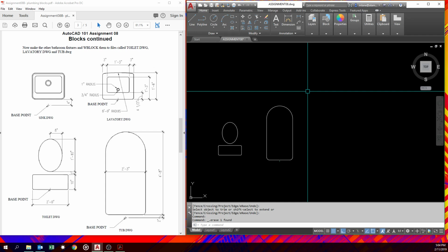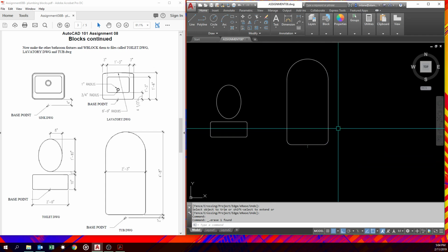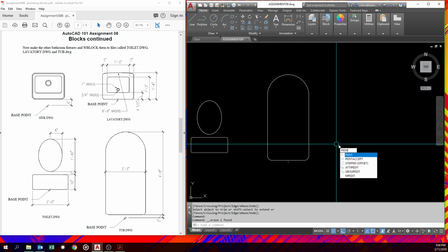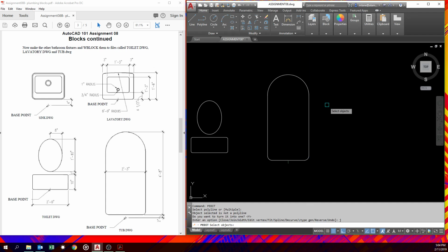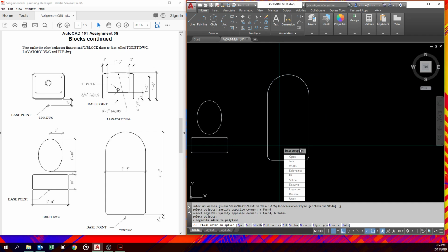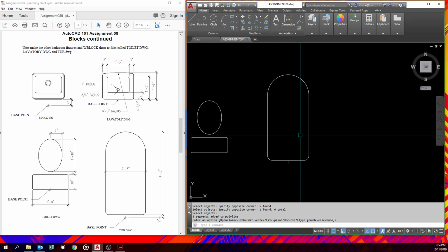And so you're fine. If we really wanted this to be all one item like it was as a rectangle, remember there's that pedit command. And it's going to ask you, do you want to turn it into one? Yes, I do. And we can join these together, J. If for some reason you really wanted to do this and have it back as a polyline, now it's a polyline. Occasionally you might really need to do something like this, but yes, don't forget that pedit does exist.